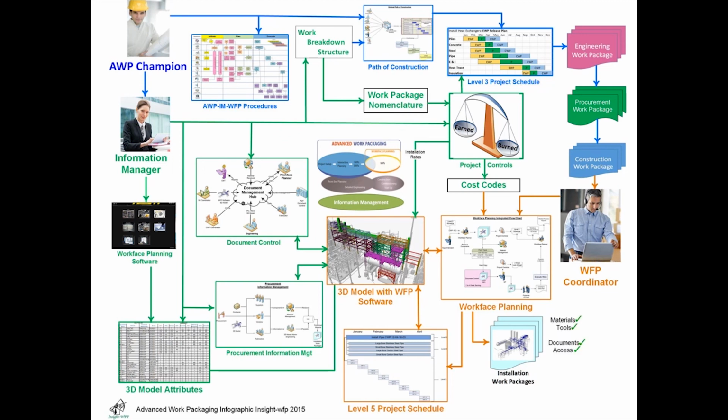As IWPs enter the 3-week look-ahead, the on-site material team bag and tank components so that they are staged and ready to ship. The scaffold team erects scaffolds to provide access. Immediately prior to being issued to the field, IWPs are rechecked to ensure the latest revision documents, prerequisite work is complete, and construction equipment is available.